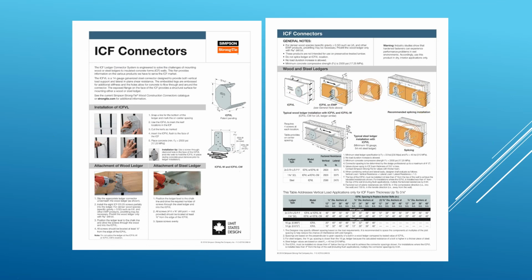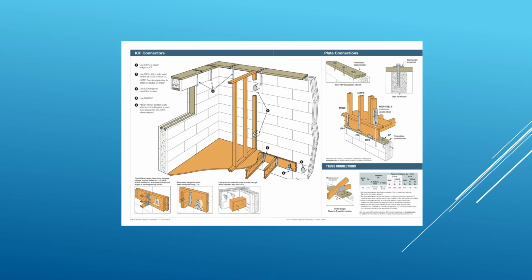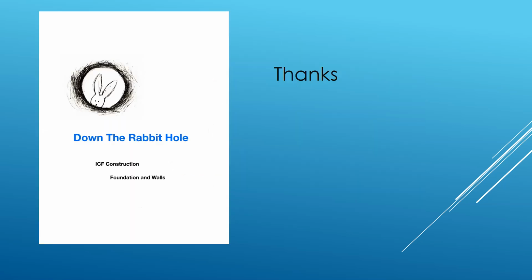I don't see any issue with these things, but again, they're not laid out in the building code. And you can see how they've got various tie downs for your trusses, straps for here. So they offer a full range of anchors, and I would assume that Simpson and then MiTek, who are now into the connection business, would also offer the same, but the code doesn't deal with those.